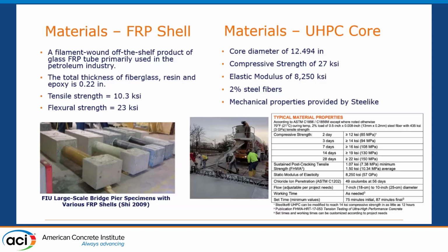And the UHPC core properties were provided by Yilei, Bill Coolidge, the president. He provided the material specifications, and also answered a lot of questions from my group. Kudos to him. And this is the material capacities and everything that was provided by Yilei. We used 27 KSI and 2% of steel fibers in the simulation.